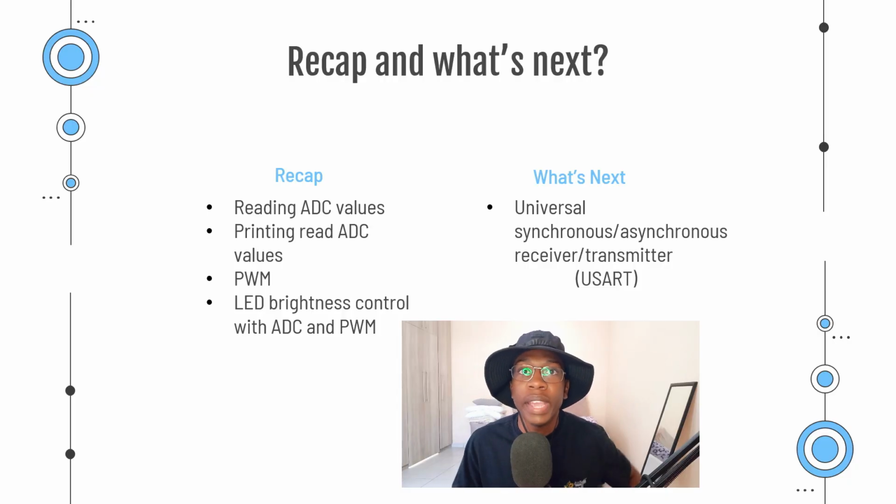In this episode, we explored ADC and how to use it to read analog signals with the STM32. We also learned how to use those readings to control the brightness of an LED via PWM, as well as how to print ADC values for real-time monitoring.